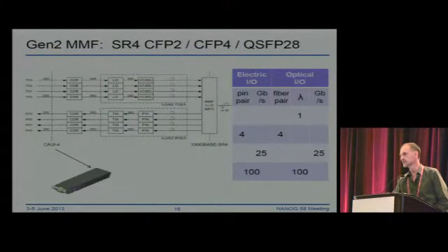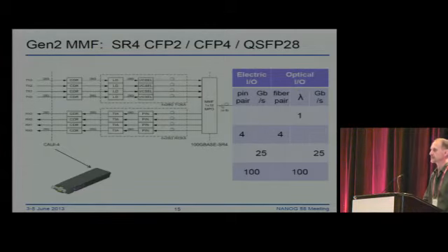Second generation, which is being introduced right now, and the IEEE is actually just completing standardizing second generation 100G. One is called, for multi-mode, the standard is SR4. So it's very similar to the 40G standard in multi-mode that's being deployed, which is 4 parallel fibers carrying 25G wavelength.